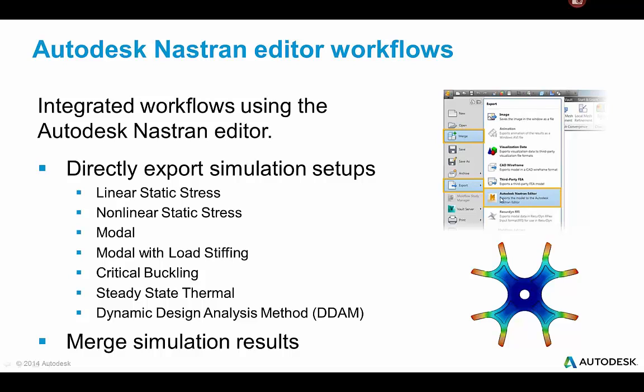Now, this export workflow supports not only the basic 6 that we have highlighted: static stress, nonlinear, modal, load stiffening, critical buckling, steady state thermal, but we've also added the DDAM method, the dynamic design analysis method. This is for those of you who are in naval shock testing. You can export your setup to Nastran editor for these 7 analysis types.